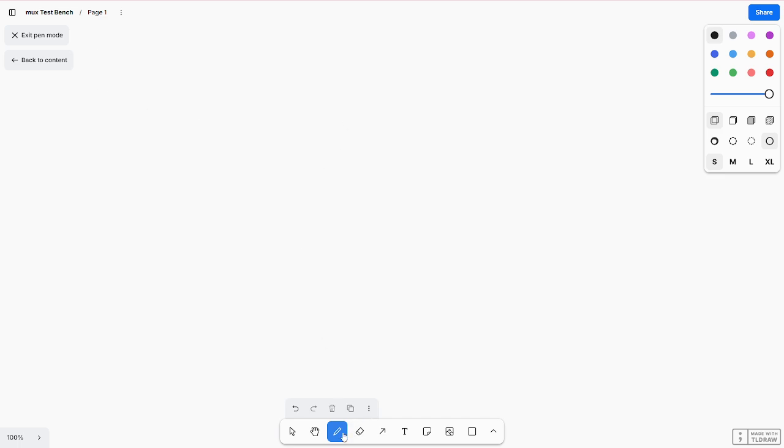If there is no default, the processor doesn't know where to go. If a default statement is not there, it will infer a latch. I will show you with one example with the default statement.